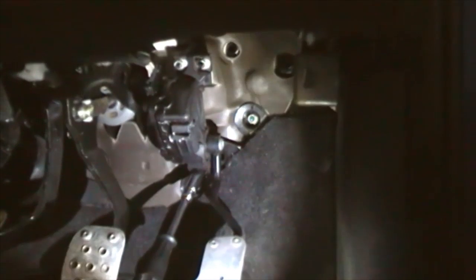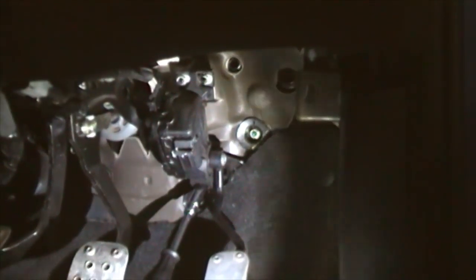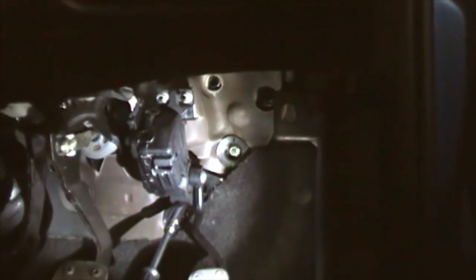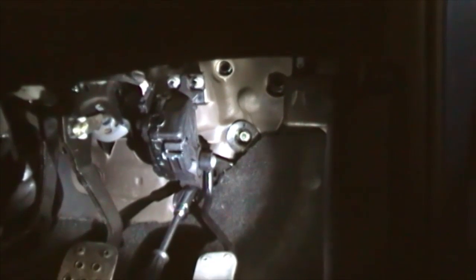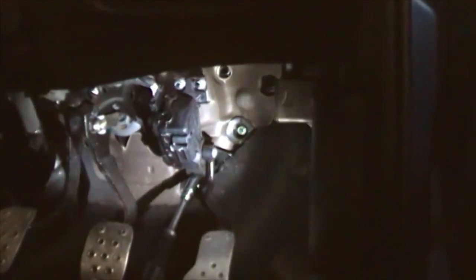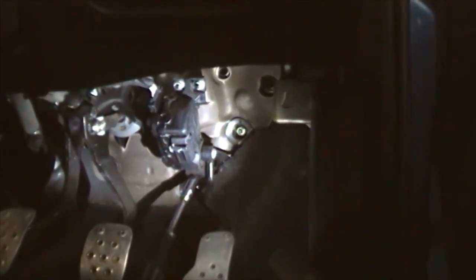The next stage is to install the throttle cable. The first part of this is to remove the original drive-by-wire pedal mechanism. Now, as you can see, there are 3 bolts holding it on, one of which has the socket on it currently, and there is a multi-plug at the top which you'll need to undo. Once these are removed, we can then show you how to install the new cable pedal setup.